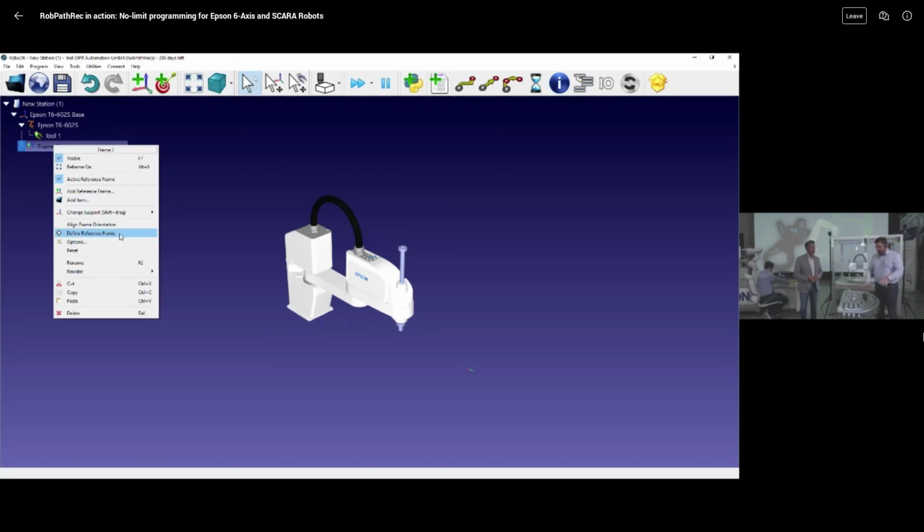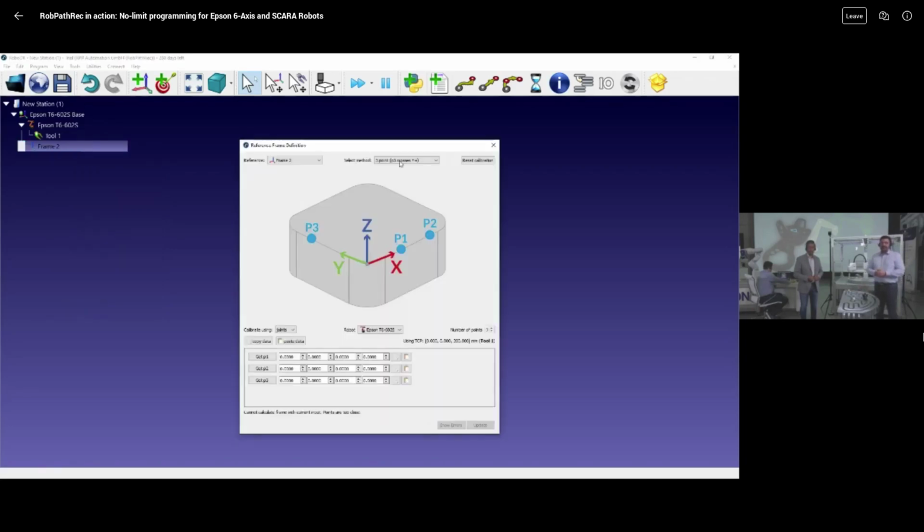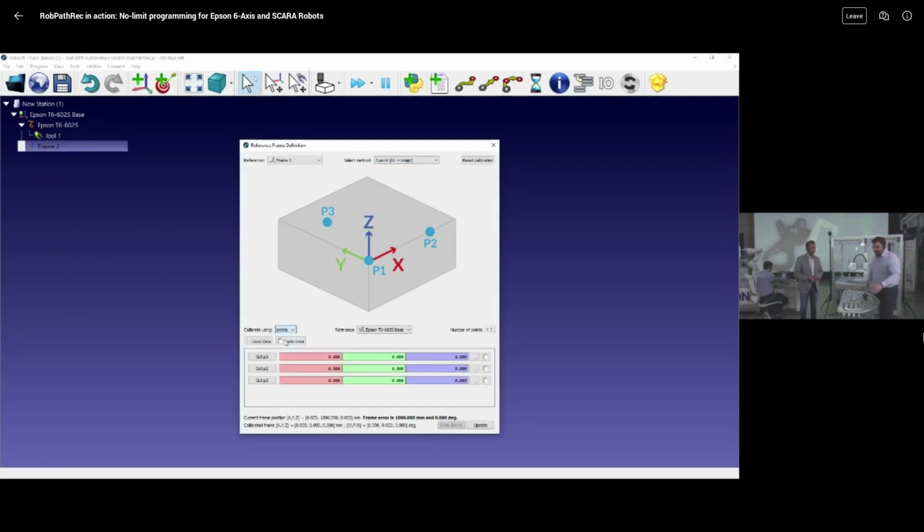Please open it, Balázs, and then we can see. With three points, very easily, 1, 2, and 3, we can define this layer, this working area. Once we have touched them with the real robot as well, noted the coordinates, and entered them into RoboDK, we have a one-to-one exact copy of what we have in front of the robot and what we have here in front of us.